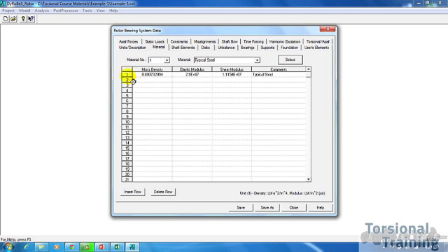So what it does is it populates this first row, and the mass density that it calculates is 7.32 e to the negative 3, I believe. Again, don't forget we're dealing with consistent English units, so we have density in terms of pound force second squared over inch raised to 4 instead of the classic pound mass over inch cubed, and the shear modulus 1.154 e to the 7 psi, pound force over inch squared, and the elastic modulus.